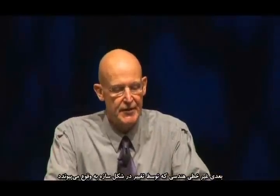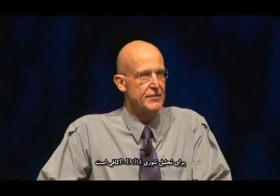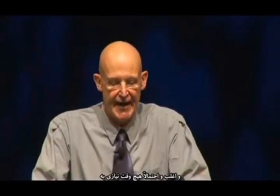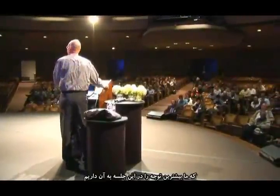Then there's geometric nonlinearity, which is caused by change in shape of the structure. And there are two forms of this. One is the p-delta theory, and the second is the true large displacements theory. And one of the things I'll emphasize is that for seismic analysis, p-delta theory is perfectly adequate. You almost never, and probably never, need to do large displacements analysis, and if you do, you're simply wasting computer time. The material nonlinearity is the more complicated of the two, and that's which I'll give most attention to in this session.